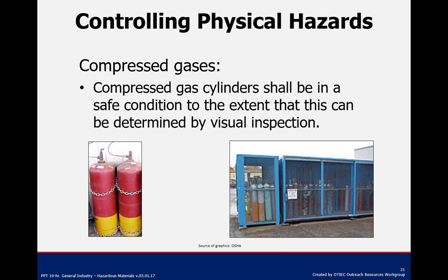Cylinders of oxidizing gases, including oxygen, except those on a welding cart that is used on a regular basis, must be stored at least 20 feet away from any flammable gases or separated by a 5 feet high, 30-minute minimum fire-resistant wall. Oxidizing gases also must be stored away from combustible materials. Not something we really have to worry about at Gold Cross, but good information to have, and we do store them in appropriate areas away from all of this type of material.